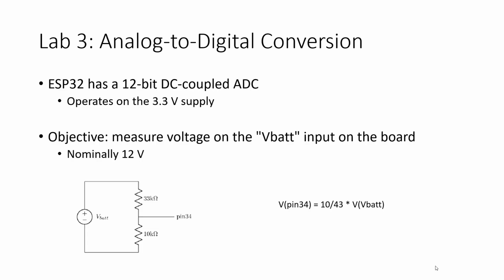Software-defined radios use an ADC to directly sample the voltage from an antenna and then use a Fourier transform along with some demodulation logic to actually read radio signals in software, which is cool. But you need a really high-quality ADC for that, and that one's usually AC coupled, I think. This one's designed to get an idea if your battery's about to die. That's the idea, and so that's what we want to use it for.